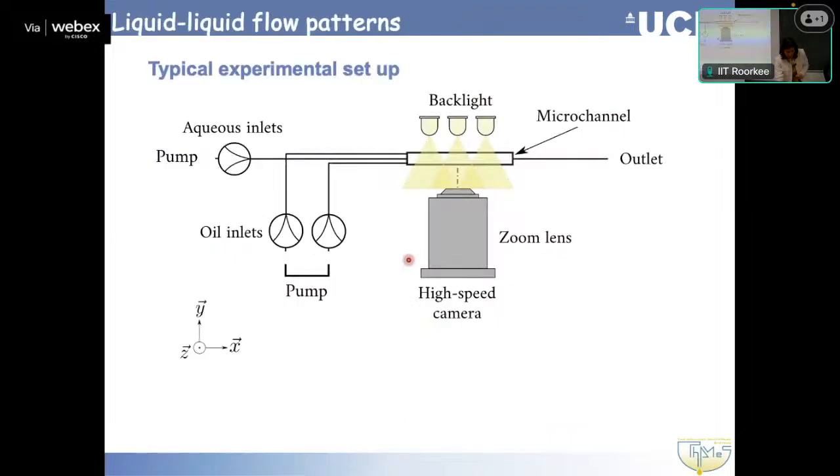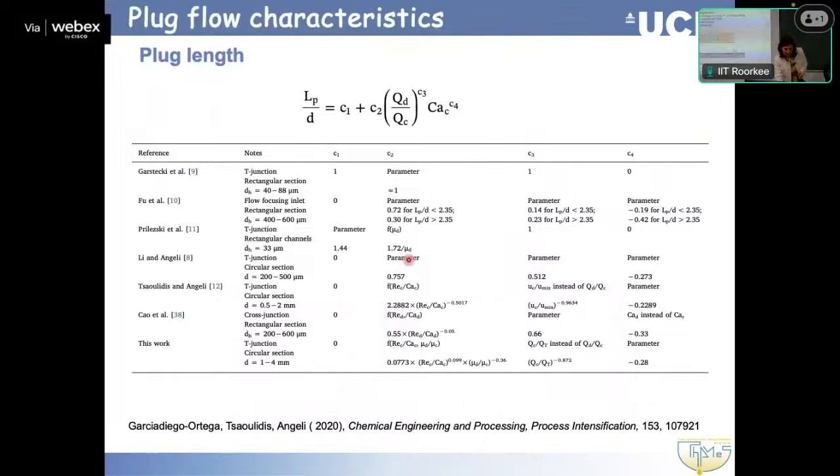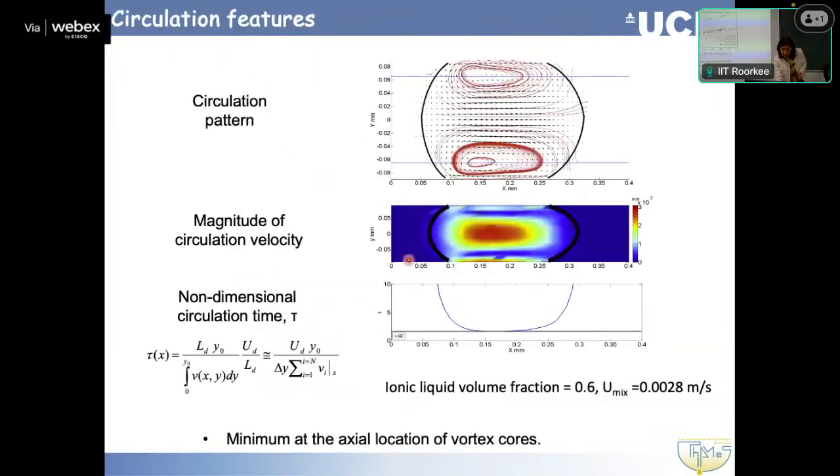Don't know if it shows in this graph here, but to measure pressure drop, you can have T junctions, with the pressure port at one part of the channel and the other open, or you can have two pressure ports to get the pressure difference. It's easy, especially if you don't have, with microfabricated channels, you might have to think of that in advance. For us, in this case that we're using just tubing, it's quite easy to attach a tube, T junction, and get your pressure drop. So pressure drop can be important.